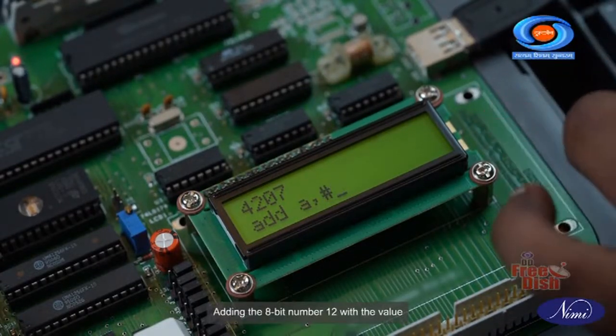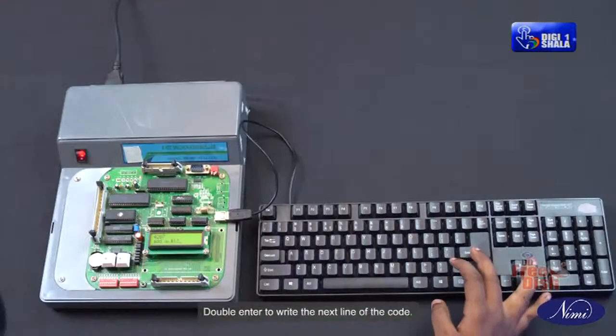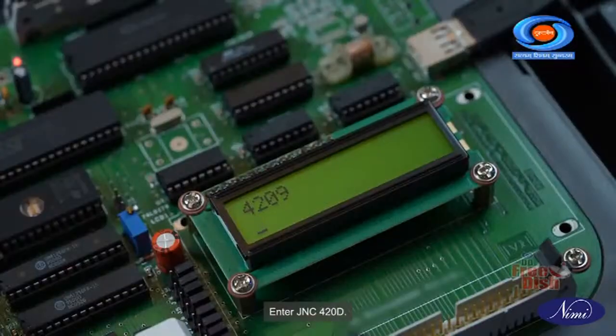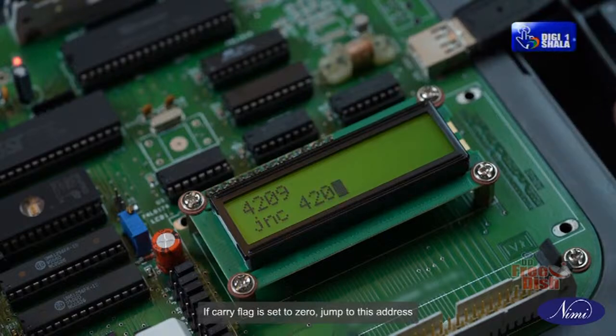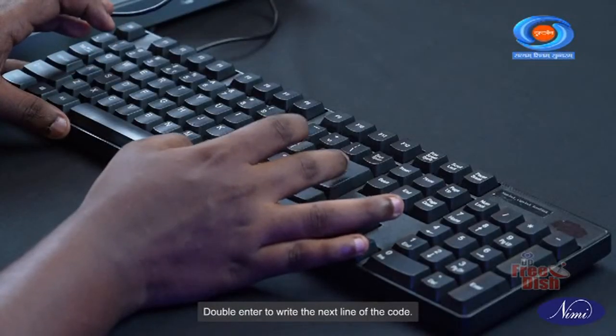Adding the 8-bit number 12 with the value currently in the accumulator. Double enter to write the next line of the code. Enter JNC 420D. If the carry flag is set to 0, jump to this address, or otherwise go to the next address. Double enter to write the next line of the code.